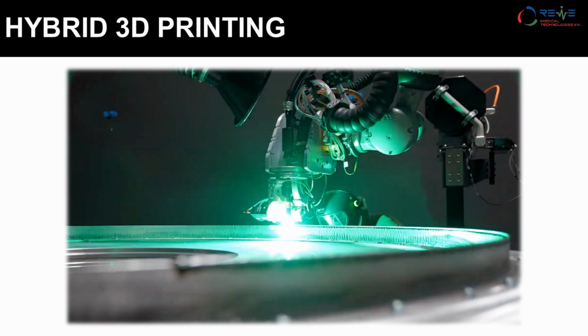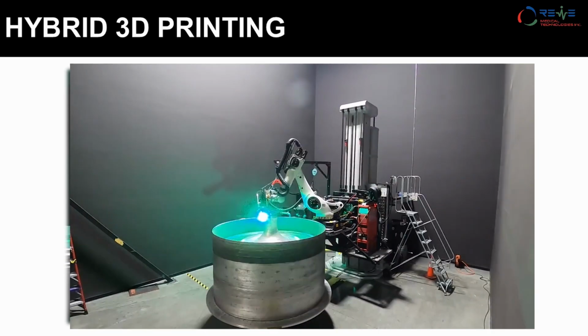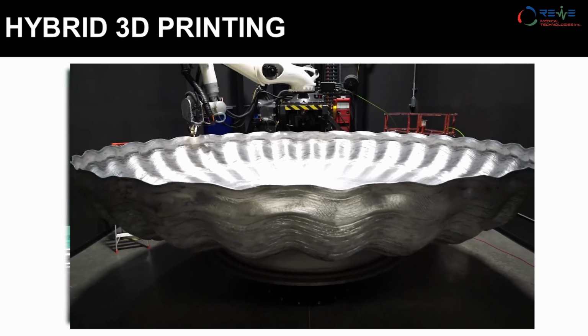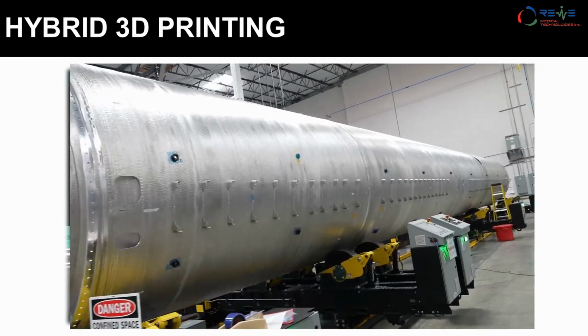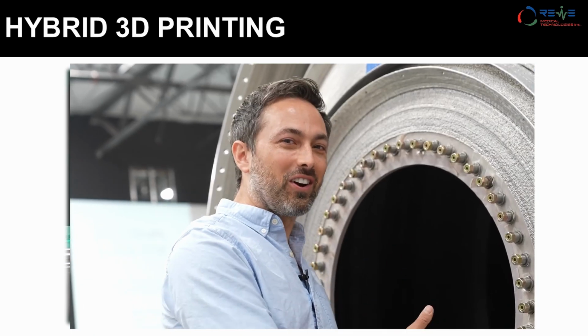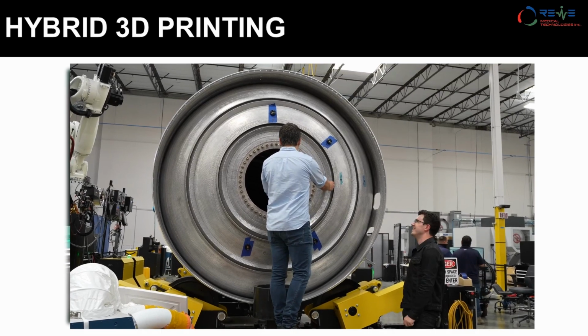There's a laser that is simultaneously welding the wire in the form of beads, and it's putting the wire over there. And simultaneously, a pulse arc welding system is also integrated inside it that is merging the layers, and that is their principle. So they've used different technologies: laser, FDM, and the third is pulse arc welding, and they've created this hybrid technology. This is their unique concept, and they can produce pounds of metal. They made their first rocket in under 60 days, fully functional, fuselage, shell, everything.